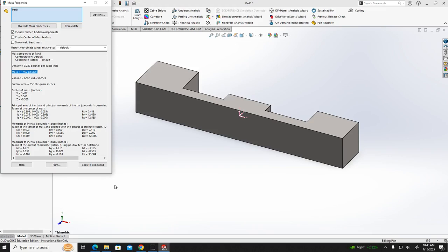I have a question: I extruded and I need to figure out how to go back and edit the other sketch. You can see this is the Boss Extrude command, and under that you have a sketch option. Just double click that, go back and edit your sketch, and then extrude again. Maybe you can delete it. Edit sketch, right there.